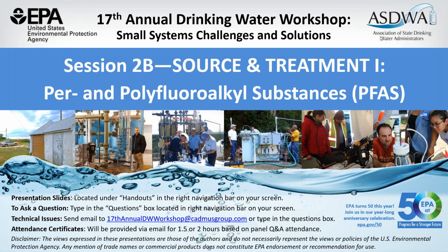One thing I think is worth adding on that question, that makes it difficult, is we've got a utility that has granular activated carbon installed, and partly what they're wondering is, is this large plume coming off of a PFAS source that's not too far away? Is that moving towards us in the ground, and at what levels could we see? They have treatment right now, but they're worried about a doomsday scenario where all of a sudden this plume hits them at levels that they can no longer treat for with the granular activated carbon.